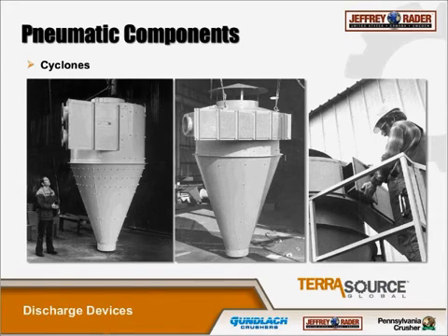So the way this works is that the air-to-material mixture enters a cyclone, then it spirals around the body of the cyclone very quickly, but the velocity is going to decrease because of the friction. Material is held against the sidewalls while the air begins to move inward. Material keeps on slowing down until it reaches the bottom, and it drops out in a spiral motion out that